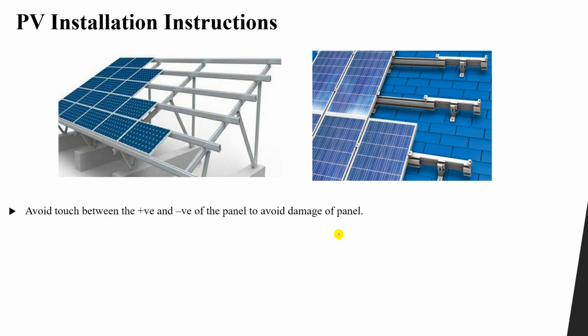The first one, you have to avoid the touch between the positive and the negative terminal of the panel, or to be more specific, avoid forming a short circuit between the two terminals, because it may lead to damage of the panel due to the very high short circuit current.